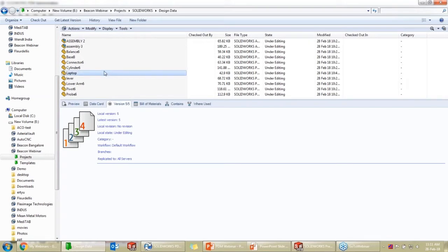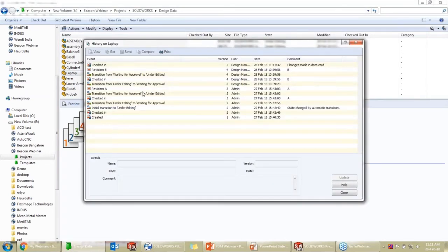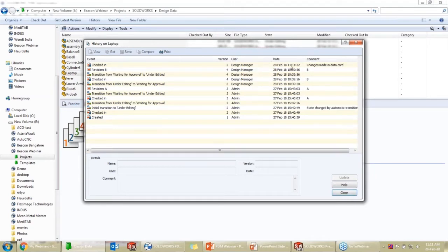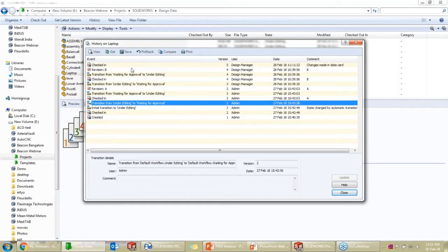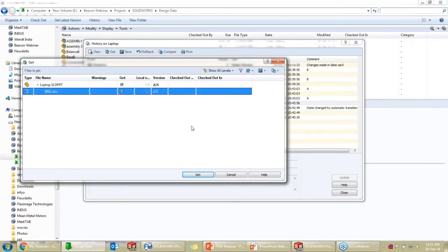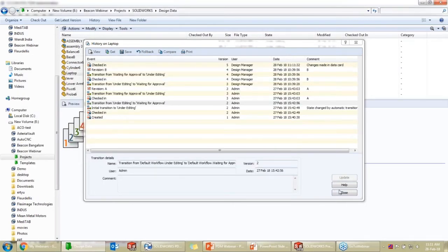You can see that previously we saw two types of symbols that were present. The first one was an equal to symbol, meaning this version that is present in my local machine and also on the server are the same. And then the next one was the red color symbol, which notified that I have the older version. And then here comes another one, which is green in color, and it tells that I have a locally modified file and the others in the organization only have the fourth version that was created. So what I'm going to do, I'm going to perform a check-in.